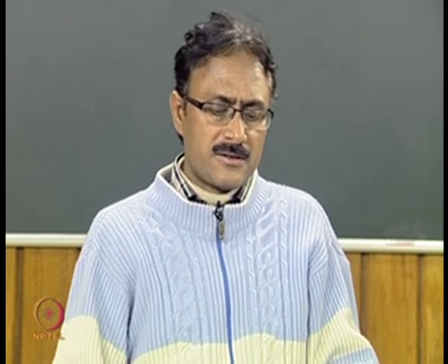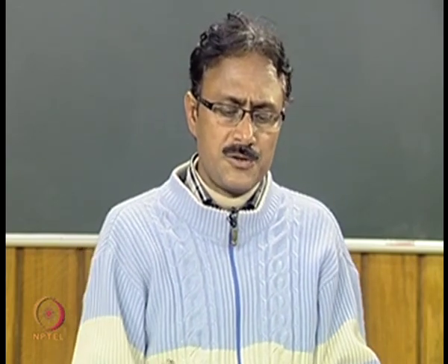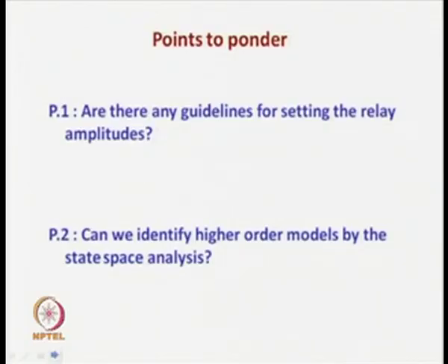Now, some points to ponder: are there any guidelines for setting the relay amplitudes? This issue we have already discussed earlier. The relay amplitudes can be set judiciously, keeping in mind the type of waveforms we are obtaining from the relay test of many practical systems.